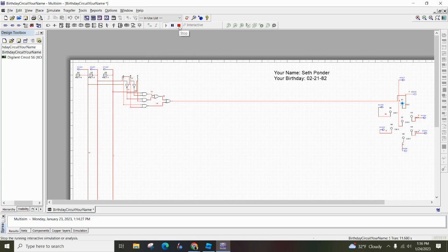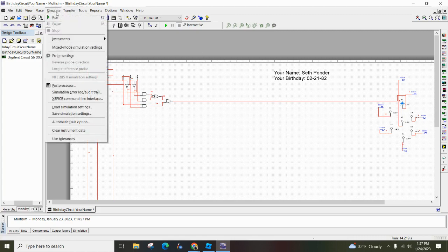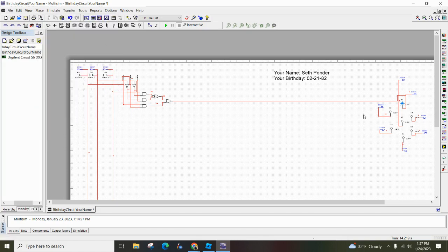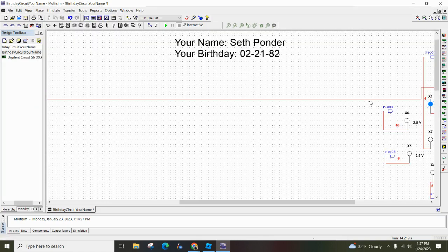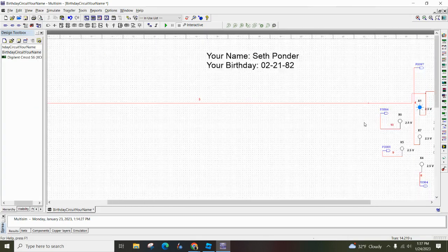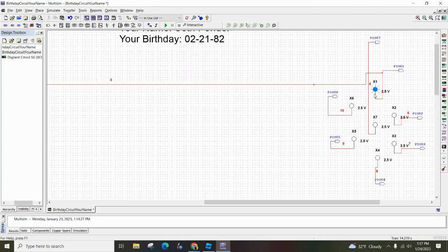Before you start wiring everything, I highly suggest wiring one segment, testing that one segment, and making sure it works. Okay, and then moving on. Fortunately for me, if I add another junction, because my A light is the same as my D light, I'm going to go down here.